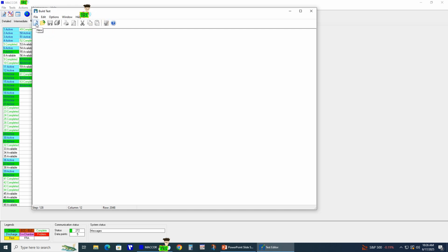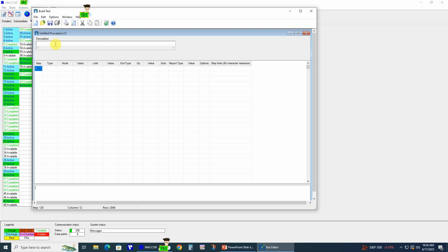Let's choose new test, and here is the description. You can write the name of the script; I am going to write the rate capability test. You can write whatever you want, and then we will write the script. So the first step is rest, and the step time should be around 5 hours or 10 hours, up to you.